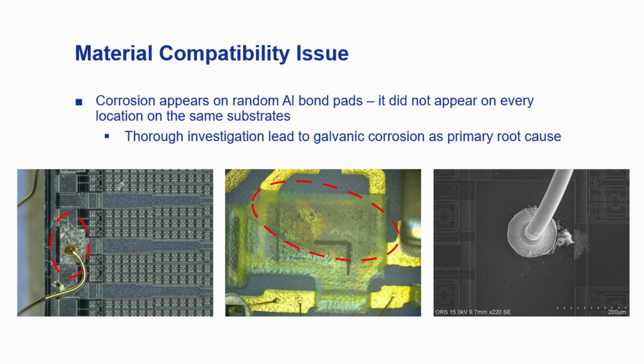Talking about customer case studies, I would like to mention a military and aerospace customer who were mainly focusing on power electronics. They were manufacturing DCBs and IGBTs, where an aluminum wire was bonded to the gold pads. In this case, when we used an alkaline cleaning agent with improper corrosion inhibitors, we found that the gold pads were reacting and forming a white residue corrosion, which was due to the impact of galvanic corrosion.